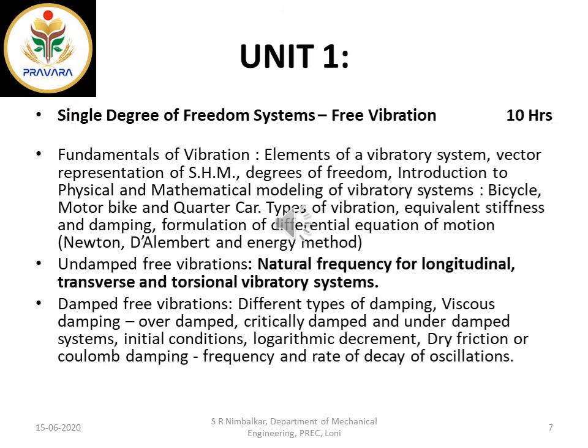So when you apply resistance to this energy, the energy is lost to overcome the resistance. Got it? When the energy is lost over this resistance, definitely the vibrations come down. Coming down of the vibrations is the decrement, isn't it? Decrement in the vibrations is represented by the logarithmic decrement. So that is one part.